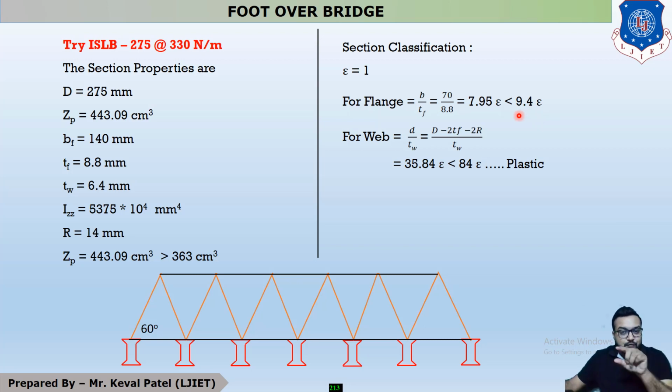After calculating for the flange, the next member is the web. You all know that the I section is a symmetric section in both ways, so for the I section the neutral axis is at mid depth. Move to the fourth row, in which it is clearly mentioned that for the web of an I, H and box section, neutral axis at mid depth.